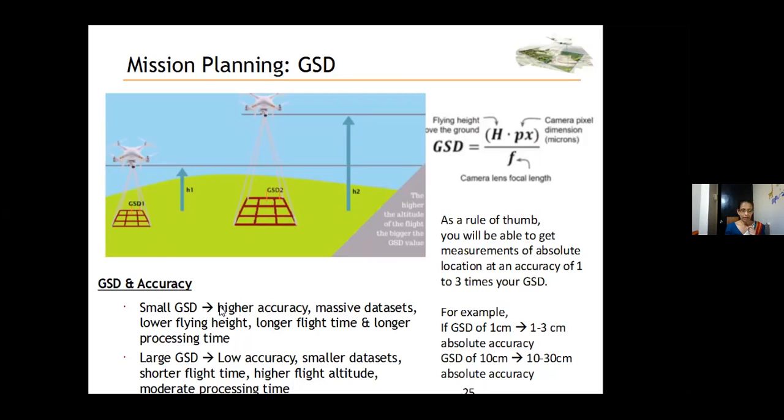The project target relative accuracy needs to be chosen depending on the project accuracy requirement. So when selecting the GSD, first assess what type of accuracy you need and to what extent. This will help you determine how to plan the flight and process the imagery.